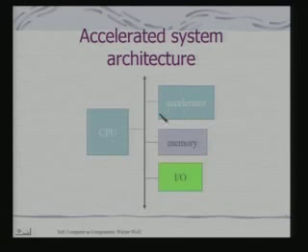Second, whether your VHDL code is synthesizing a circuit which can satisfy the timing constraints. If you are satisfied with that, then you do the mapping onto that FPGA block, and once you have done the mapping, you have got an FPGA based implementation of the function. Therefore, I now have an accelerator.